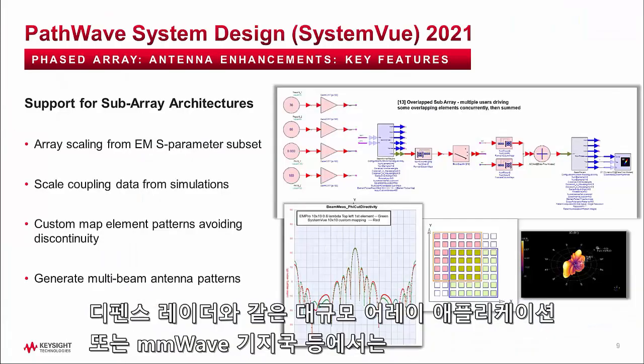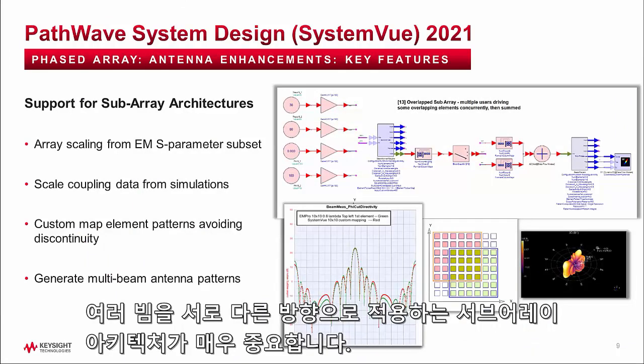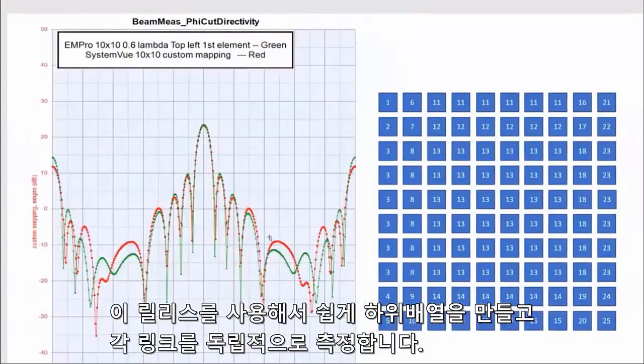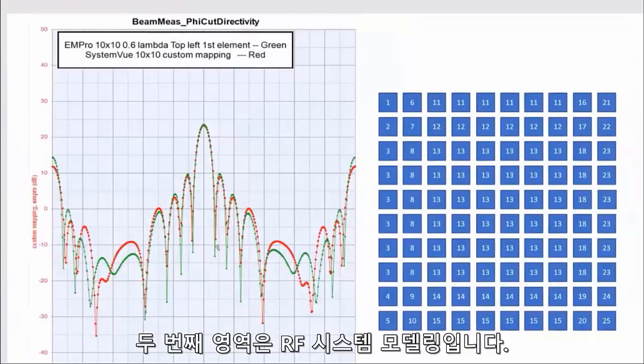In large array applications such as defense radar or millimeter wave base stations, the use of subarray architectures is critical to steer multiple beams in different directions for either target detection and tracking or for multi-user data links. With this release, you can easily configure your subarrays and measure each link independently.